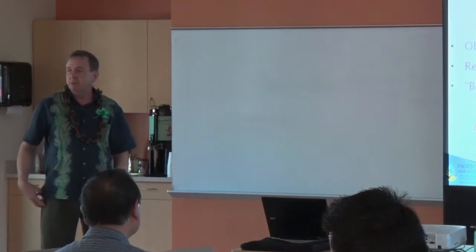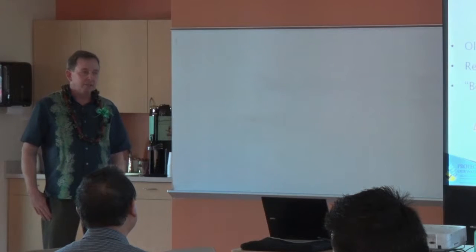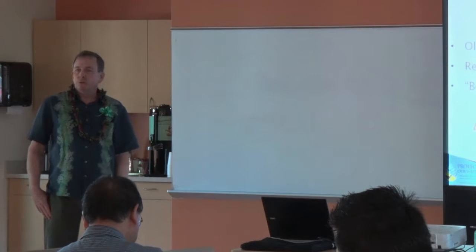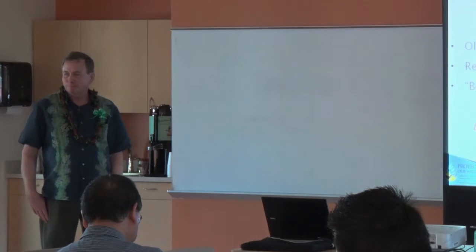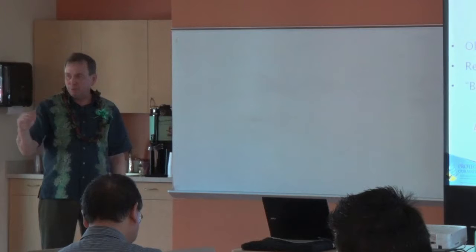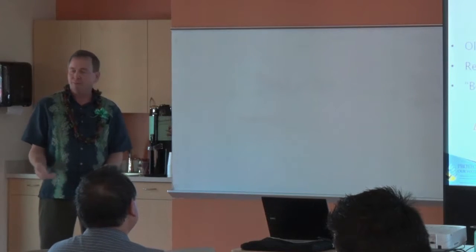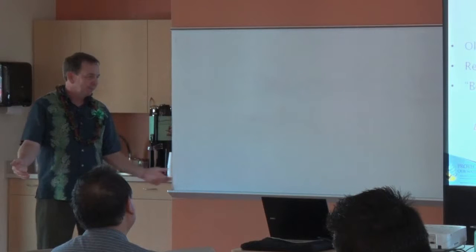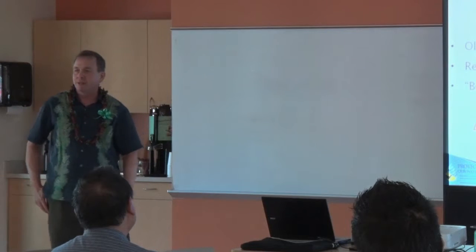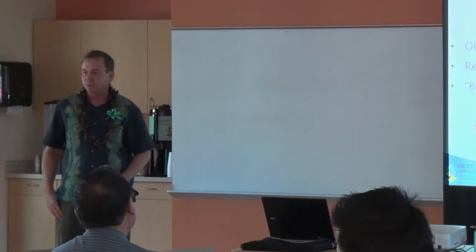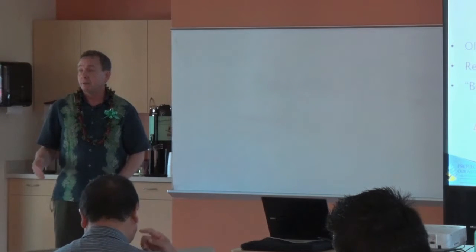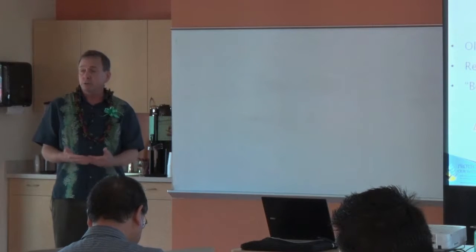I live now in Seattle and work there. In the city of Seattle, they require LID treatment for 2,000 square feet of disturbed surface. And it's even smaller than the treatment requirement. Even if you're not required to do treatment, you're required to implement LID. So if you expose base course on 10 by 20 from here to that wall, that slice, we would have to put some sort of LID treatment on this area that we're disturbing. So it's not going away. It's here to stay. So it's something we've all got to learn how to use and how to deal with.